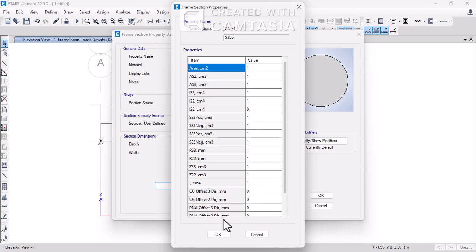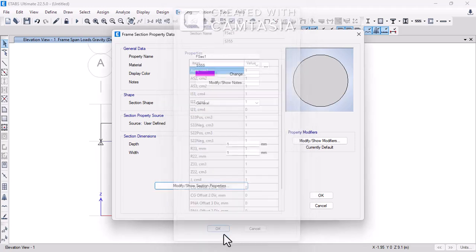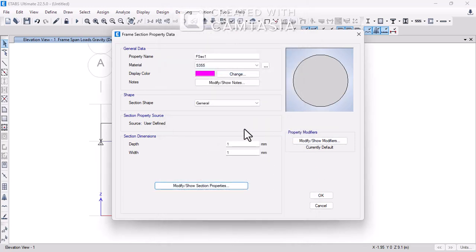If I change it like this, the axial deformation, shear deformation, torsion, and deflection values are going to be very low, so we can neglect them. That is why I chose the frames like this. Using this, we define the section properties so we can match those assumptions that we make in the manual calculations.